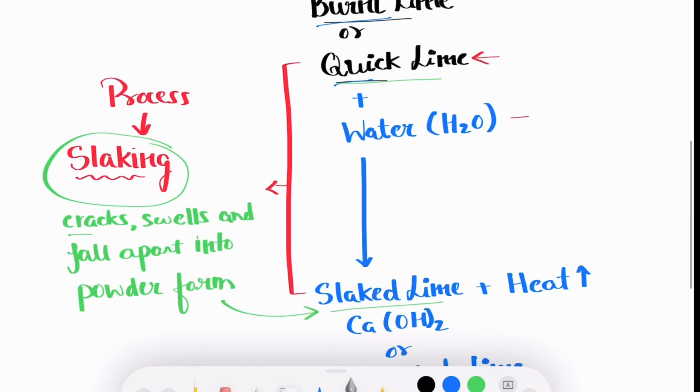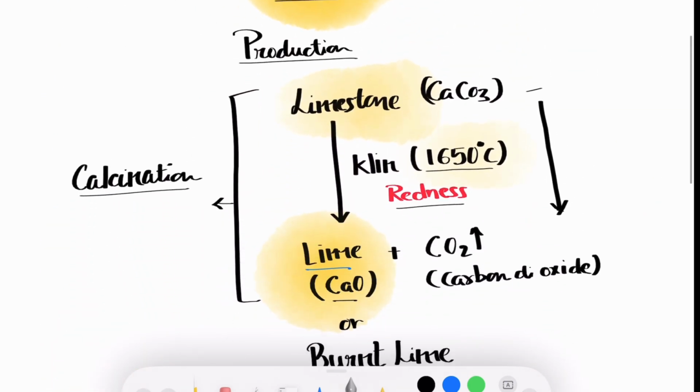Now, see what happens is lime is basically derived from CaCO3 or limestone. The property of the limestone depends upon the area from which it has been extracted. So this limestone may be subjected to a lot of impurities, in terms of chemical compounds like silica, clay, or something else. It can be some other materials, but the dominant part is the CaCO3.